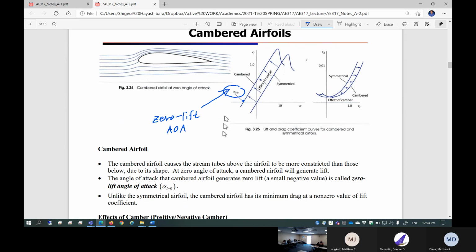Okay, so you are going to start showing a zero lift angle of attack for a cambered airfoil. It's always slightly negative angle of attack. In other words, you have to pitch down this much to have zero lift, because with the cambered airfoil you are already producing lift at zero angle of attack. So obviously, when you attach your wing to your fuselage, you have to think twice. If you use a symmetric wing, of course, this is the attachment angle. But if your wing already has camber, the attachment angle is probably going to be shifted slightly to the negative angle. Otherwise, it's not very good. So you have to think twice about that. But what is the great benefit of it?